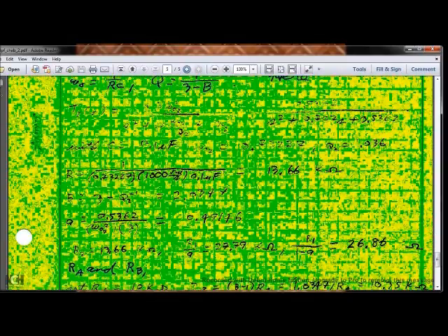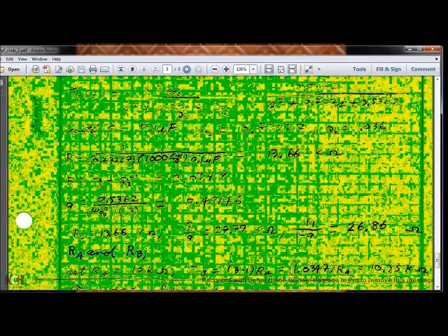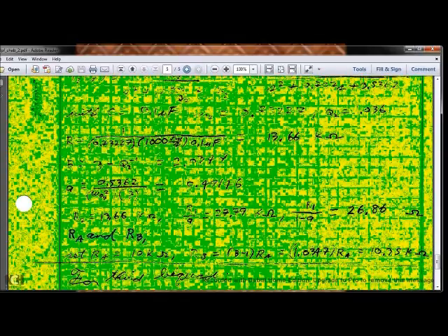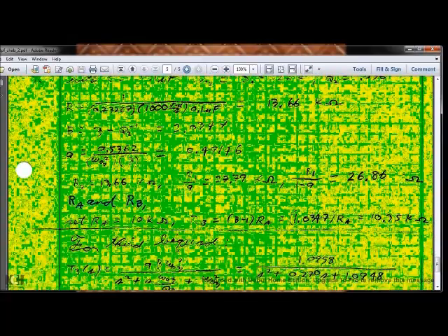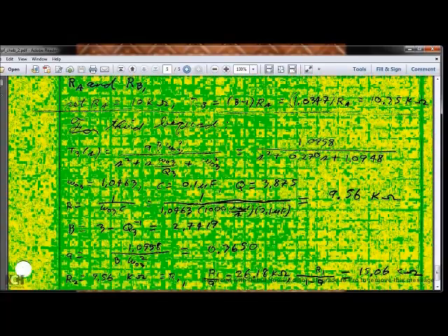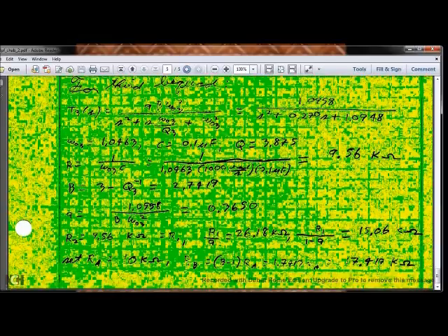We calculate R1 and R2, 13.66 kilo ohms. And B is 3 minus the quality factor to the minus 1. And A, unfortunately we used A twice in our derivations here. We have our A factor and our B factors. R1 over A, we calculate that. R1 over 1 minus A. For RA and RB, RB is equal to B minus 1 times RA. So we have that for both of our second order sections. The third biquad is calculated here.